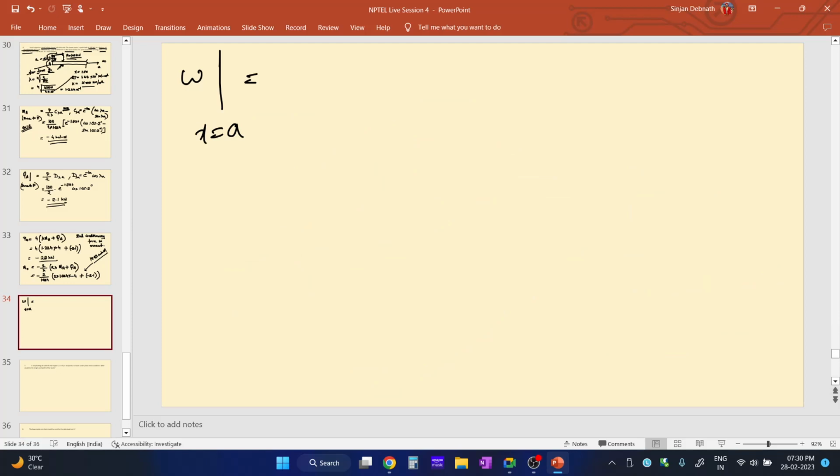Okay, so deflection at X equal to A. If we add up all the deflections, you will get P lambda by 2K, this is the deflection due to load P, that is the 100 kilonewton, plus P0 lambda by 2K into A lambda A.